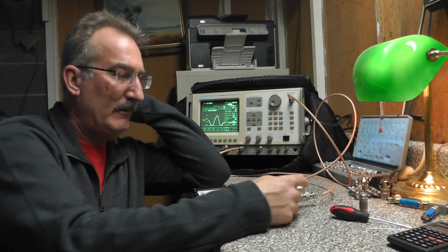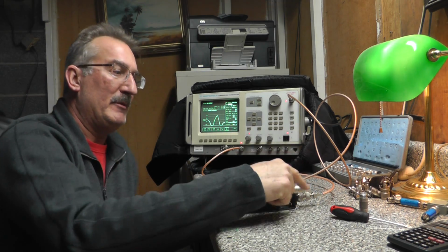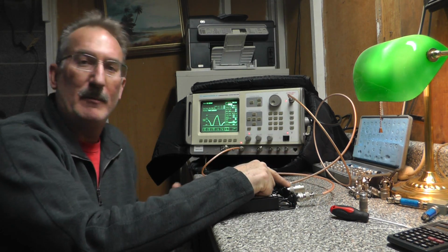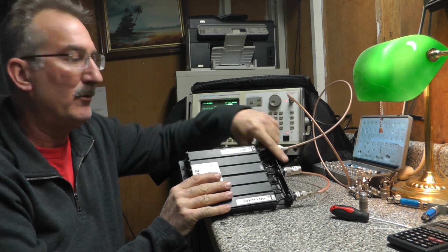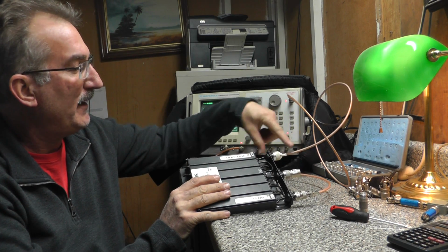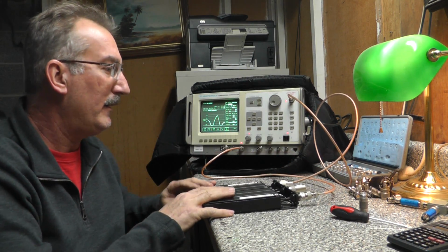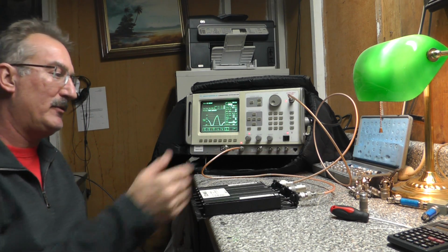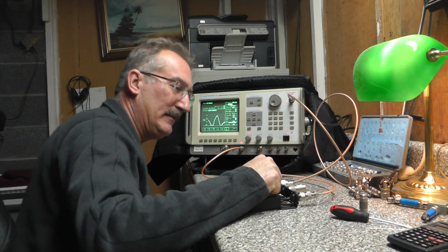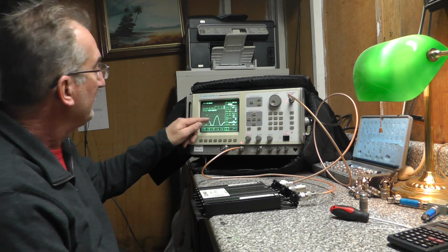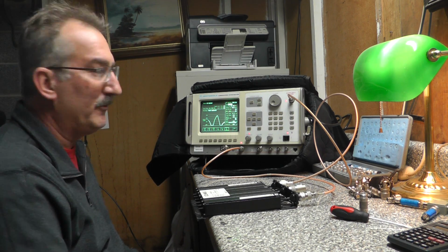Okay, so here we've tuned both sides, and now I have it set up to put a transmit frequency into the transmit side. I have a dummy load on the antenna port for some impedance matching, and I have our output from the receive side going into our input on our analyzer. Now we should be able to see both notches, because these are connected together, remember, at the antenna point, and we do see both notches.